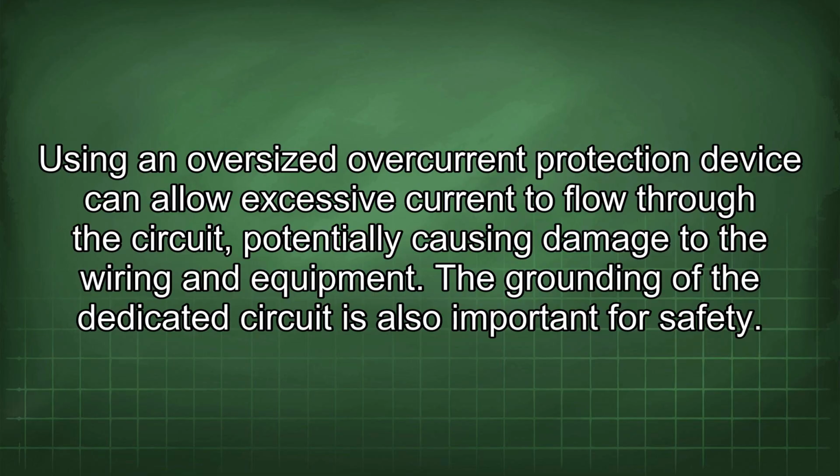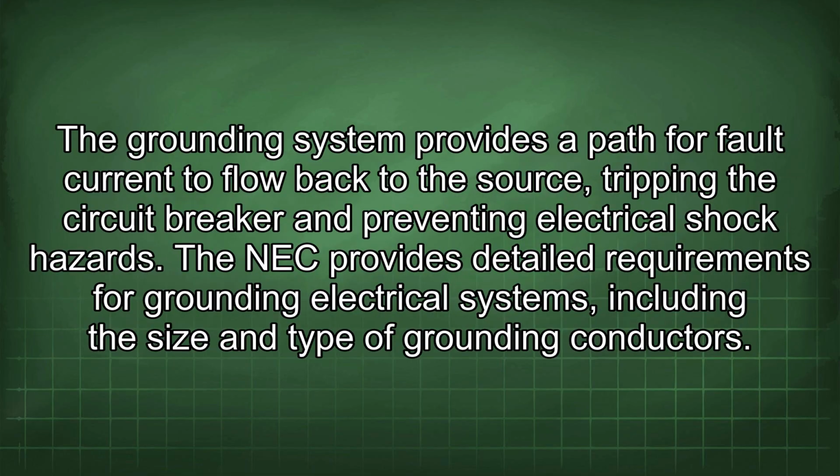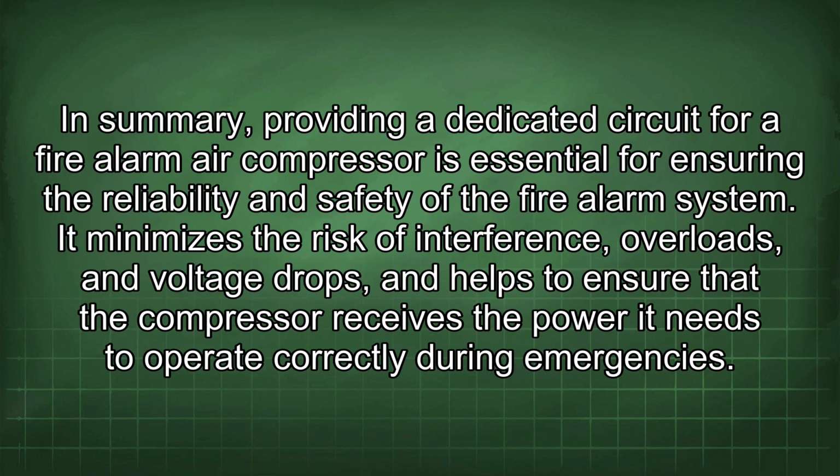The grounding of the dedicated circuit is also important for safety. The grounding system provides a path for fault current to flow back to the source, tripping the circuit breaker and preventing electrical shock hazards. The NEC provides detailed requirements for grounding electrical systems, including the size and type of grounding conductors. In summary, providing a dedicated circuit for a fire alarm air compressor is essential for ensuring the reliability and safety of the fire alarm system.